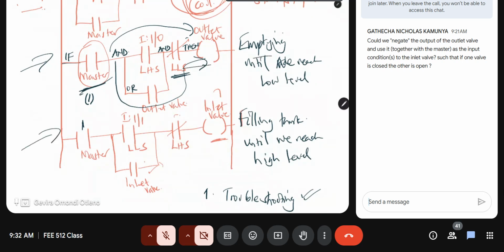Then I go to the second rung and run it independently to see how it works. But now, if I had borrowed conditions of rank 2, put them in rank 3, conditions of rank 3, put them in rank 4, and so on, then it becomes a very tedious process. I'm not saying it doesn't work. I am saying it may work, probably will work. But your challenge is always in debugging your system or having to troubleshoot to figure out where a challenge is.